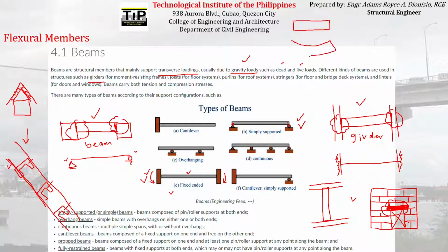And from strength of material or mechanics of deformable bodies, you have learned na once na nag-bend yung beam, yung upper portion niya experiences compression. So, parang nako-compress yung mga fiber or yung mga hibla that compose the whole beam. And then yung mga fibers or hibla dito sa bottom or sa ilalim ng neutral axis, they experience what we call tension stresses or tension forces.